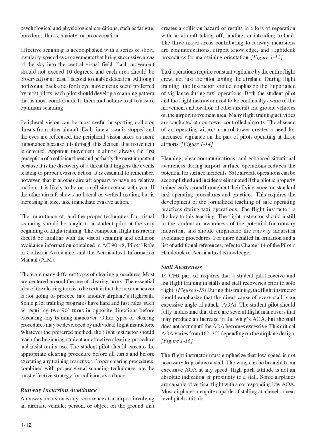Figure 113: taxi operations require constant vigilance by the entire flight crew, not just the pilot taxiing the airplane. During flight training, the instructor should emphasize the importance of vigilance during taxi operations. Both the student pilot and the flight instructor need to be continually aware of the movement and location of other aircraft and ground vehicles on the airport movement area.